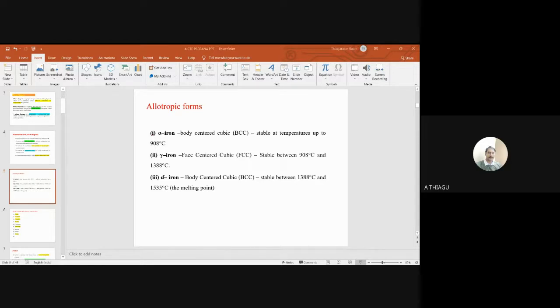Okay. So the maximum percentage of carbon in ferrite is very, very little, already I pointed out 0.025 percent. Austenite only 2.11. So you have to identify the reactions that happen in the iron carbon diagram. Is it clear? I hope you can understand the reactions for different materials. Once again, L plus S1 equal to S2 for peritectic. In eutectic, L equal to S1 plus S2, and third, eutectoid, S1 equal to S2 plus S3.